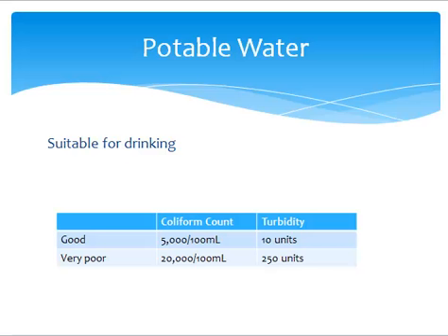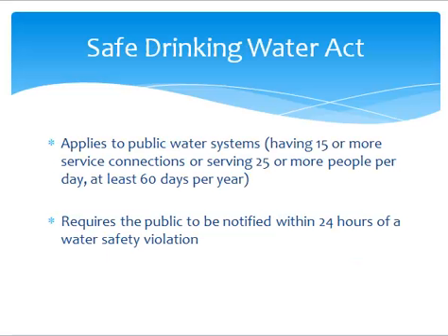The record should include the name, date, and location, as well as the water quality results and analysis. These should be kept for up to 12 years. The public and the state should be notified, and results submitted each month to the appropriate regulatory agency. Let's now move on to treatment processes. We will begin with sedimentation.